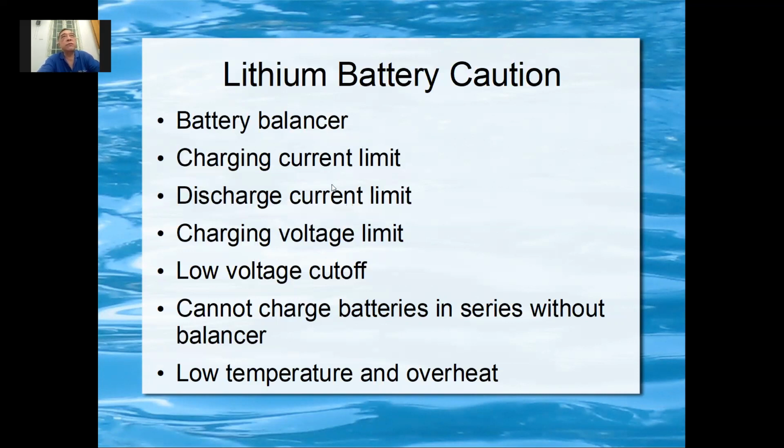Because if you discharge current too high, then the battery will heat up a lot. And then it can burn. Lithium ion will burn. Too hot, you start to burn. And when you discharge too fast, dendrite will form. Dendrite. Later I will explain what dendrite is. Then that can cause a short circuit inside the battery. That will cause the battery to burn, catch fire.